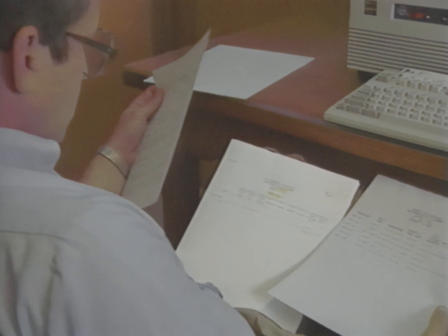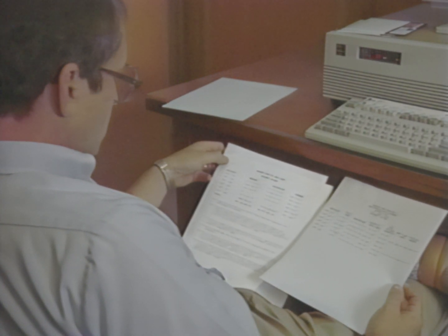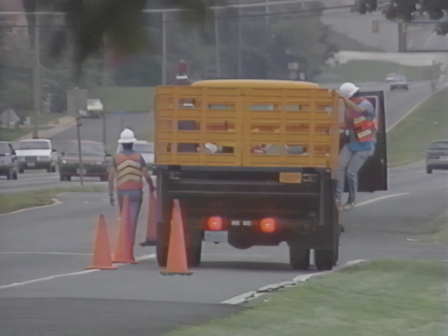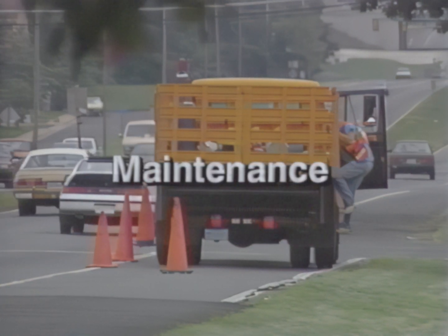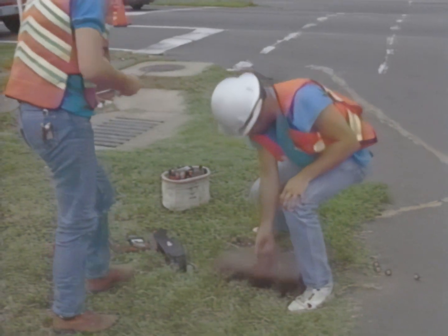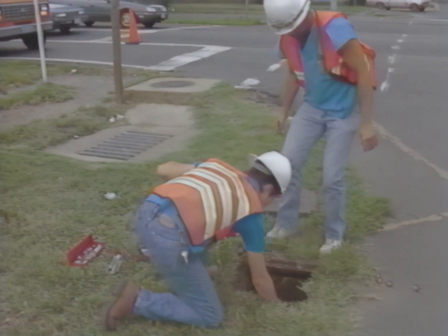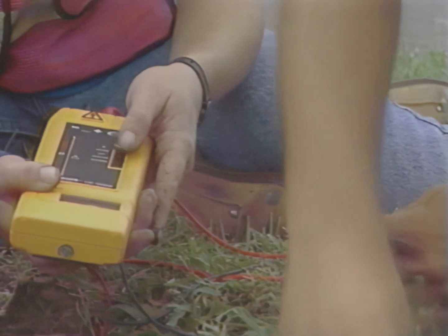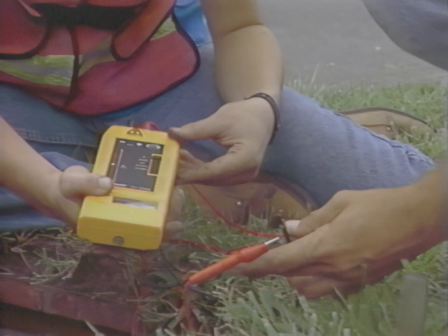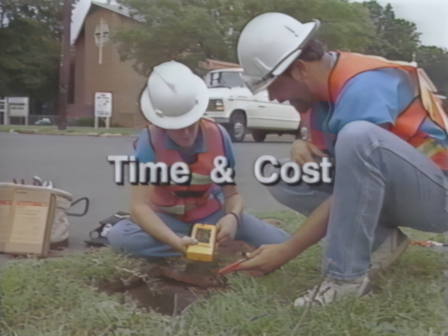Compare the benefits of choosing an expensive detector with low maintenance costs versus a less costly detector with a high repair or replacement charge. Traditionally, cost of maintenance has been the primary consideration for selecting a type of detector. For example, the rugged, low-maintenance magnetic detector is still popular despite its limited capabilities. However, when selecting a detector based on maintenance differences, remember to consider the amount of time that will be spent on maintenance as well as the cost of maintenance.